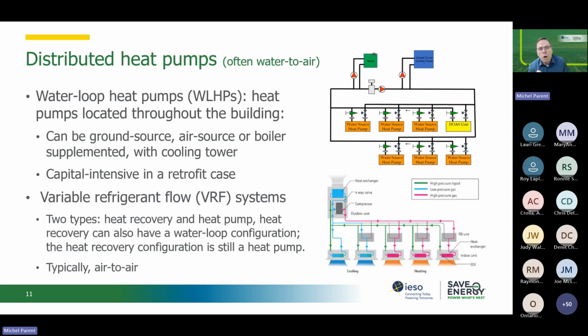And those water source heat pumps, they do have range. If you want to use a lower temperature for ground source heat pump in that type of loop, you need what's called an extended range water source heat pump. So if you've got already a heat pump in your building and you say, I'm going to go with an air source heat pump, but I'm going to drop the temperature so that I can use that heat pump more efficiently, you may hit a wall here, because your water source heat pump may not have the range to be able to use a cold source. So you've got to make sure you know what type of systems you have before you start considering it, and before you start reprogramming, obviously, your BAS.